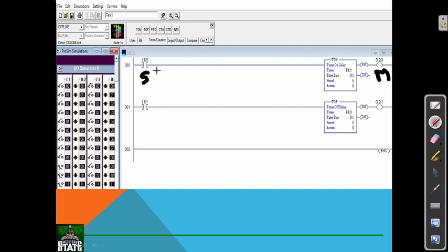If I switch on, it won't run because here I am using an on delay timer. I'll put the time of this on delay timer as 5. So if I switch on this motor, the motor will run after 5 minutes. This is the example of an on delay timer. From the name itself, you can understand that with an on delay timer, the process will have some time delay.